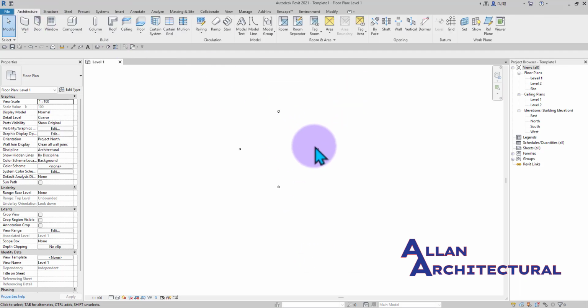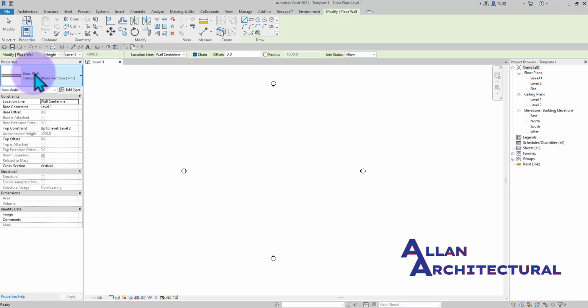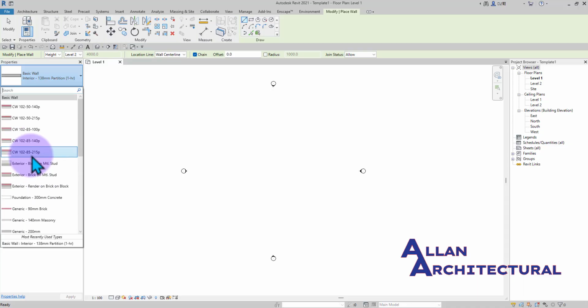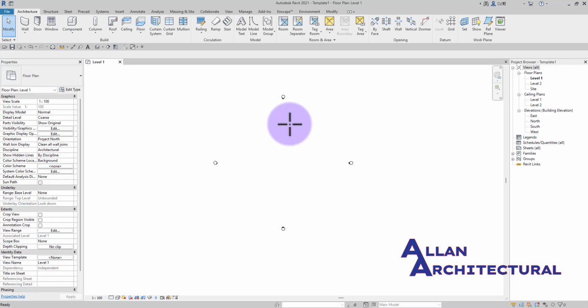So now Revit has gotten rid of that wall for me, and I'm going to show you guys in a second. I'm going to go back into the Wall tab, click on that drop down menu, scroll all the way up, and you notice we do not have that wall again in there. So that system family of that wall has disappeared, it is out of my template. I don't have that wall anymore in there. So that is how you can actually get rid of every single thing you have inside of the Revit software.